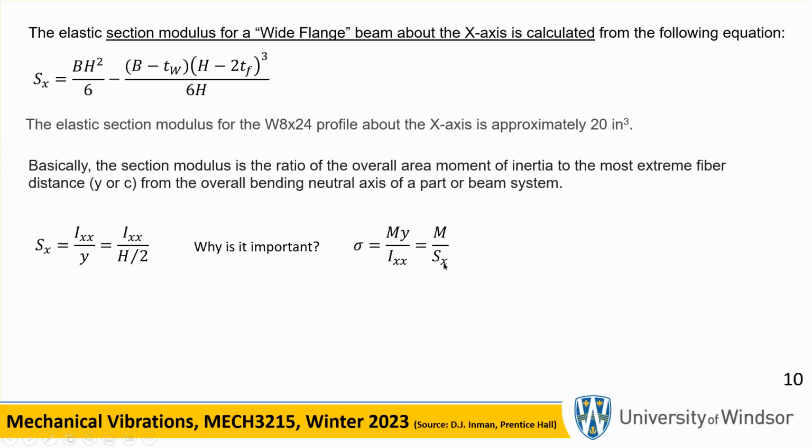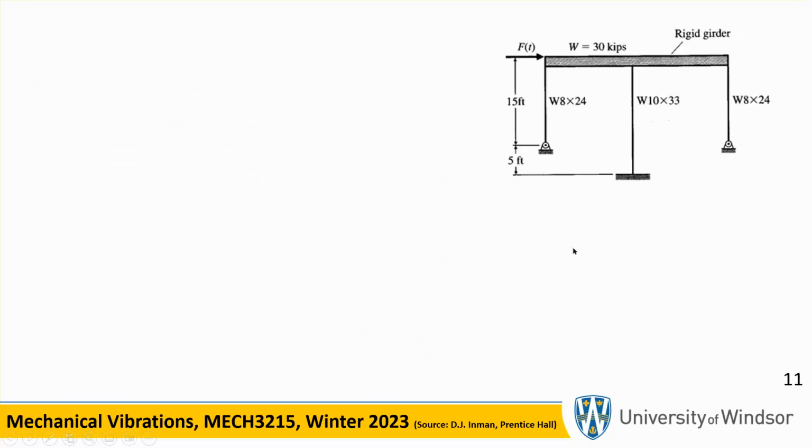So there we are. That is why section modulus is going to be useful. Now, mechanicals probably look at it like this mostly, civils look at it like that. And I told you that Sx contains the information about Ix in an indirect way. Okay, so let's go ahead and do the calculations here.